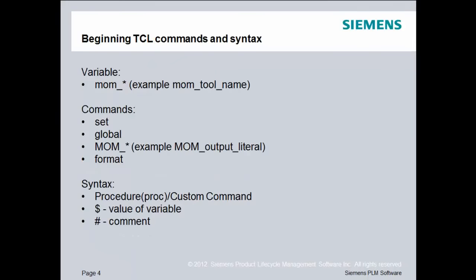We will talk about some beginning TCL commands and syntax in this lesson, but I wanted to briefly address a couple of things. A variable in PostBuilder will be listed with lowercase mom, underscore, and then the variable name. An example I've shown here is mom_tool_name.